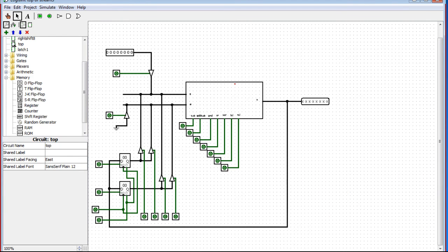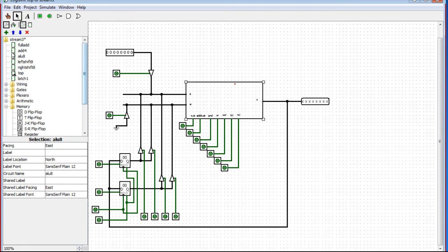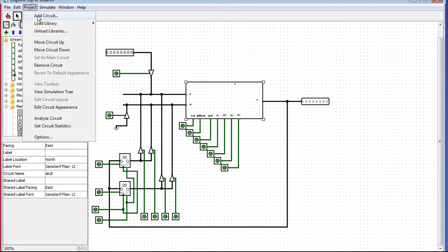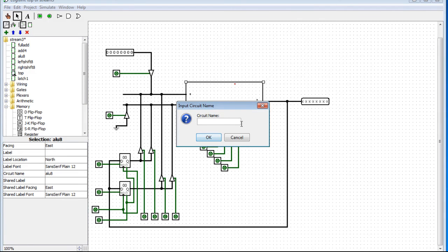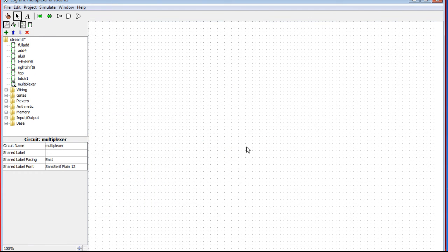And that, my friends, is memory. Another thing to tick off the list there. And we'll be incorporating that into this circuit a little bit later. But first, I want to talk about one more pretty important circuit element, component, if you will. And that's the multiplexer. What the multiplexer lets us do is it lets us select between multiple inputs, and the output becomes one of those inputs depending on, again, some select bits, which are just address bits, address lines, if you will.